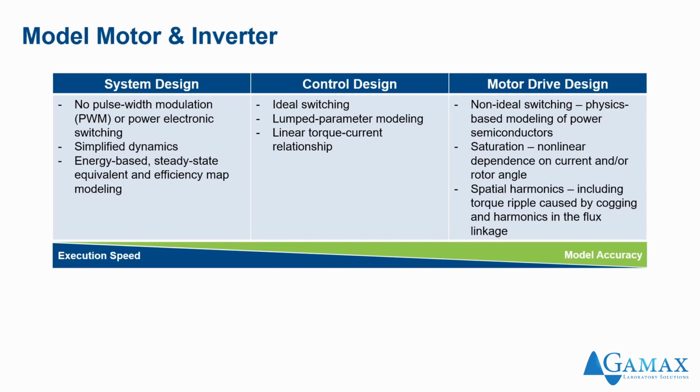To account for magnetic saturation or parameter variation under different load levels, we can incorporate finite element analysis data that describes a nonlinear flux current relationship in our motor model using the motor drive design fidelity level. The highest fidelity motor simulation can be achieved using additional finite element analysis data on spatial harmonics to facilitate the development of torque ripple mitigation algorithms and optimized drive design. With the use of Simscape Electrical, we have capabilities to model different levels of fidelity.